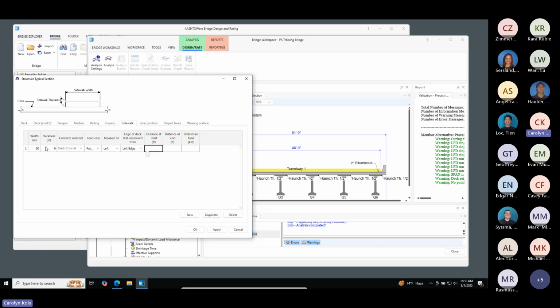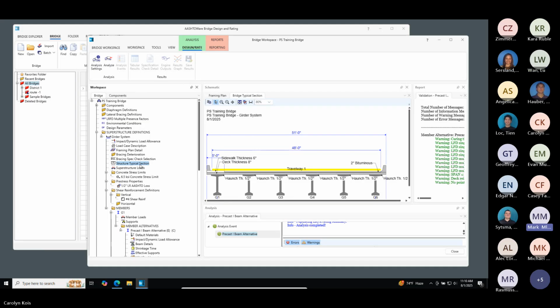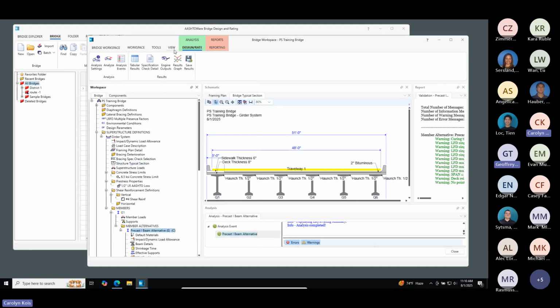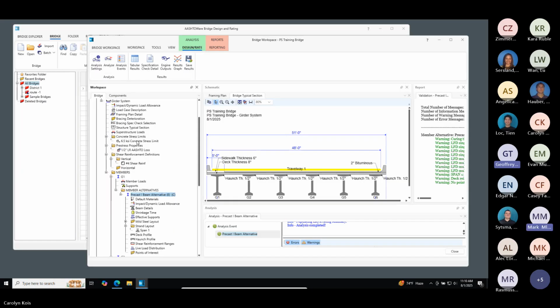Yeah, similar to how, okay, it would add it in. Well, I forget how we changed it, but I think it's treated similar to the adjacent live load, where you subtract it off of the capacity. You're talking about the pedestrian load, so it's a numerator value for the rating rather than adding to the live load. Yeah, that's what I would think. And that was recently changed, wasn't it, Mark? There was a change in the last few years.